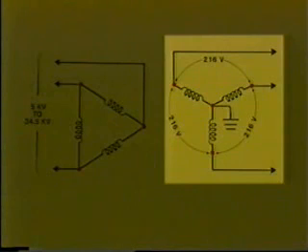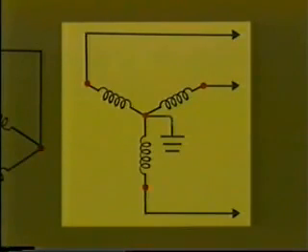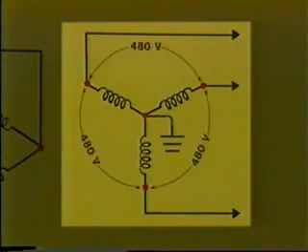Network transformers are typically designed for a secondary voltage of 216 volts line to line, that is 125 volts between one phase and the neutral. Newer, large, high-rise buildings may be equipped with network transformers whose secondary voltage is 480 volts line to line for the supply of three-phase equipment.